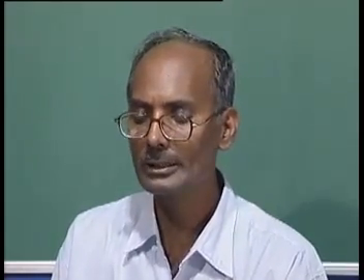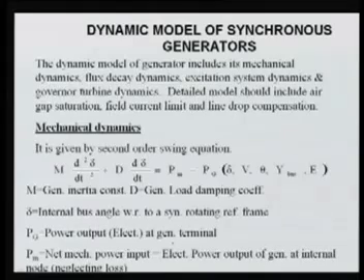Dynamic model, let us see the dynamic model of synchronous generators. The dynamic model of the generator includes its mechanical dynamics. Mechanical dynamics means, again, the swing equation. Flux decay dynamics, again the detailed representation of the machine itself. Then excitation system dynamics, that is, the machine is equipped with fast acting voltage regulators, AVRs, and then we